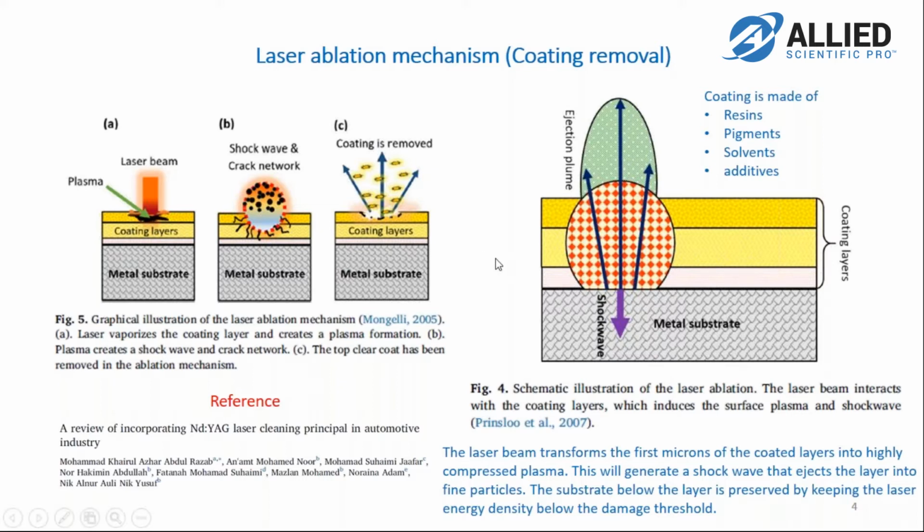Depending on the type of coating, you could also have the laser beam going through the coating and reaching the metal substrate, heating that, and then the plasma generated by the metal could ablate the coating. That's called a spallation process, which I'll talk about later. In the case of paint on a car, for example, the absorption is by the coated layer, not by the substrate.